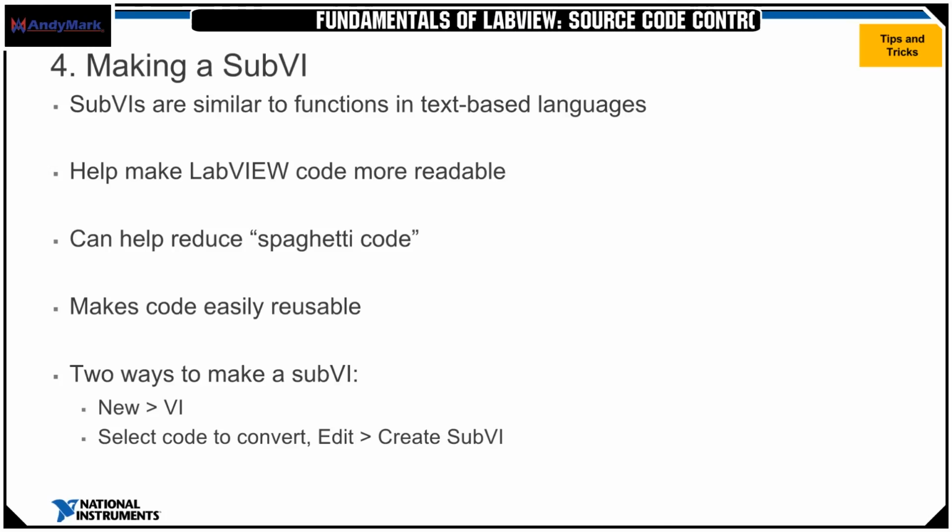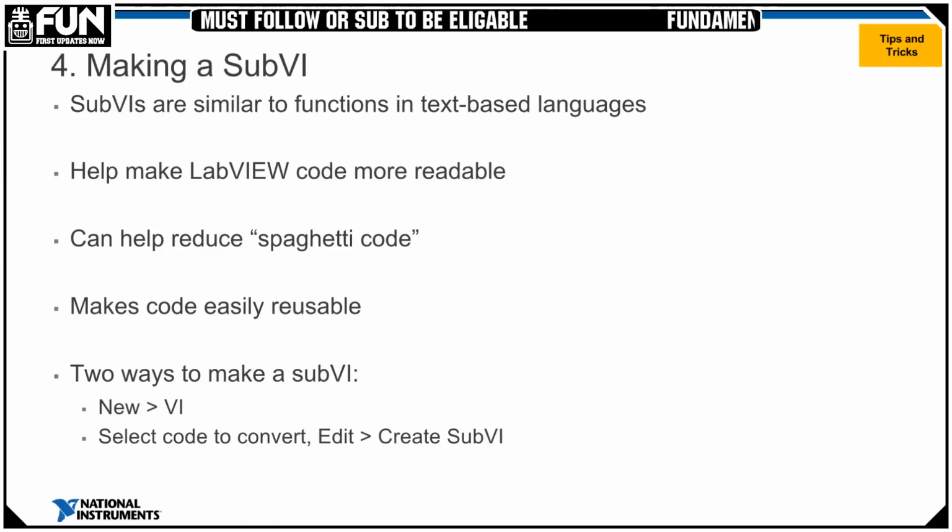That's what we call LabVIEW code that's out of control. Wires are going everywhere. It starts to look like a pile of spaghetti. I highly recommend Google image searching LabVIEW spaghetti code. You'll see some very terrifying pictures of LabVIEW. But SubVIs also help make your code easily reusable because you can drag them out of the Project Explorer window into any other VI without having to rewrite the code you already wrote. We would all like to write less code.